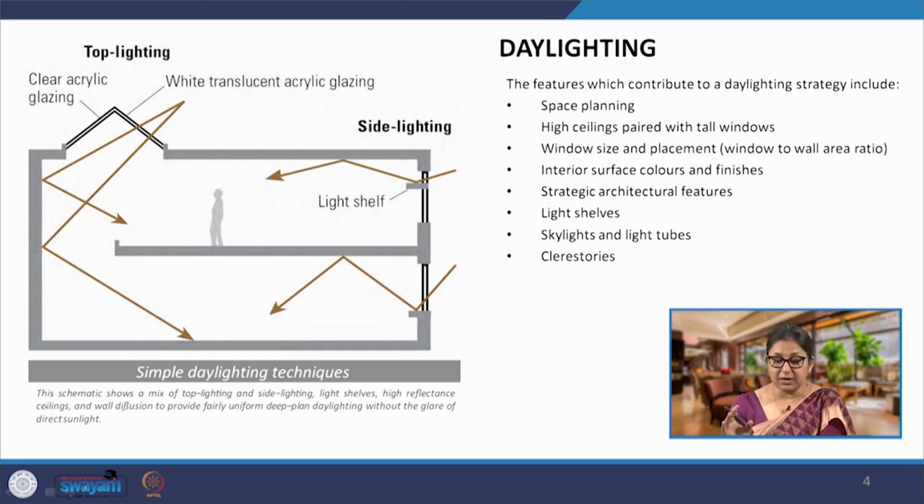When we are talking about daylighting, the first thing to be planned is how the fenestration, the windows, have to be provided, and where they have to be provided, how much they have to be provided, and how they have to be shaded. So, we are talking about windows first, or all other forms of fenestration. We have two types of fenestration. One is the top lighting. We clearly know the skylights and the atrium tops as the top lighting, and then we have windows for side lighting. We have different types of windows which we will come to.